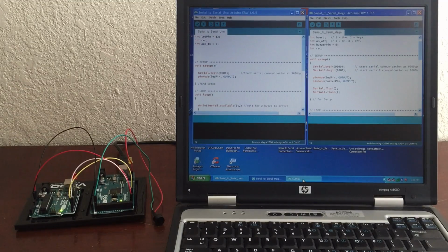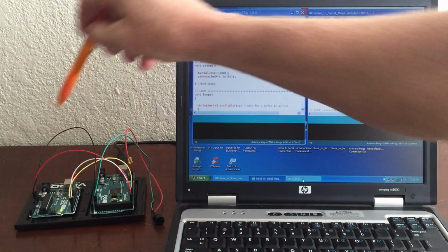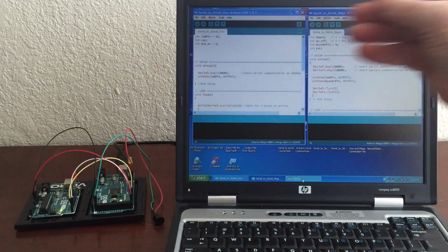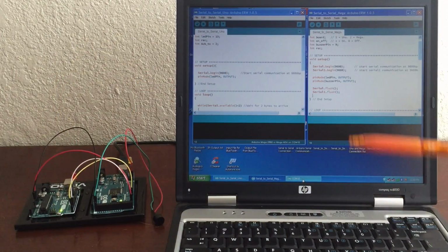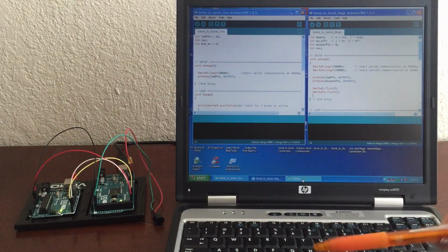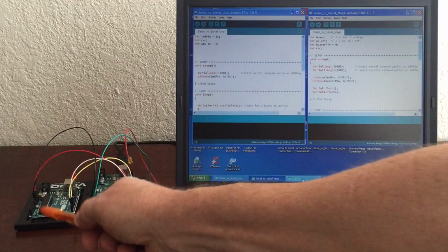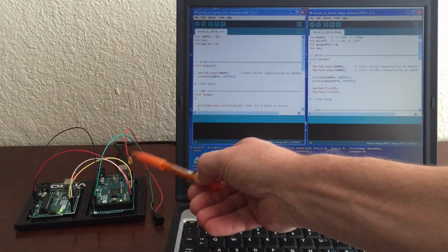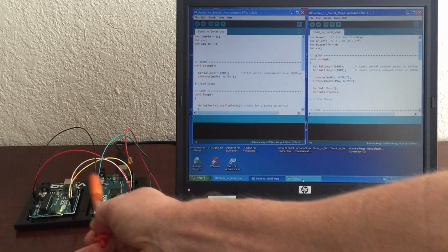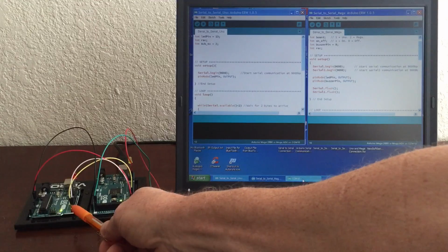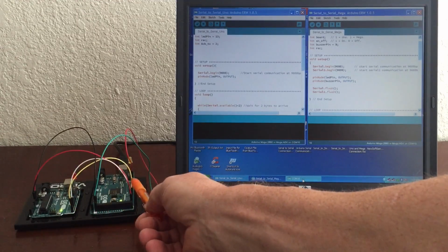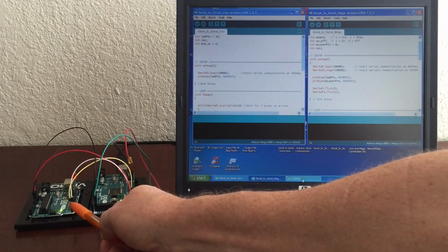Another thing to keep in mind is that these LED lights here and here will light up using an input of 1 or 0 for on and off, and 1 and 0 for either the Mega or the Uno. Once you select the Uno, you'll be talking over the hardwired serial communication, from serial 1 to the serial port on the Uno.